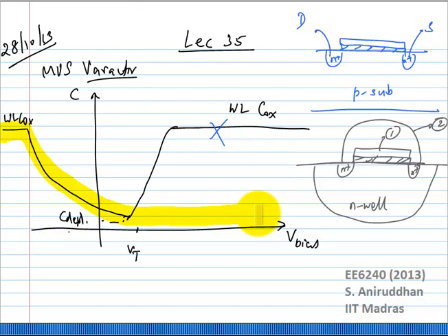For example, we talked about a PN junction. There are specialized processes available where there are specialized PN junctions to give you very large Cmax by Cmin, as well as a more linear behavior of frequency versus control voltage, right? So you dope the junctions as well as grade the doping of the junctions to get a better behavior, okay, for specialized use as a varactor. All of these things are possible in different flavors of the processes that you work with.